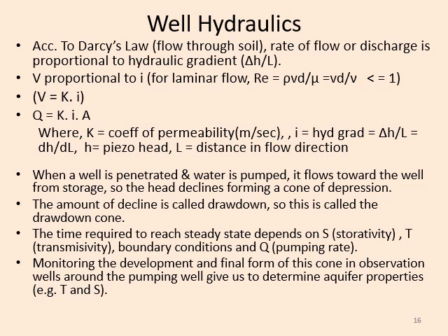So V is proportional to hydraulic gradient I. We know I equals delta H, change in head, upon L, the distance in the aquifer. So V is proportional to I.